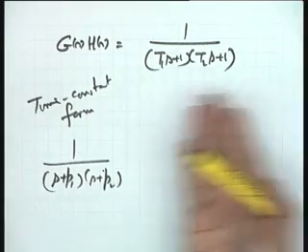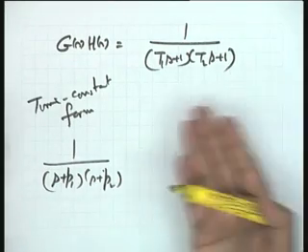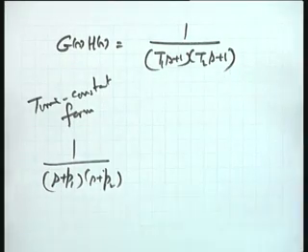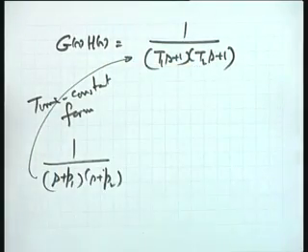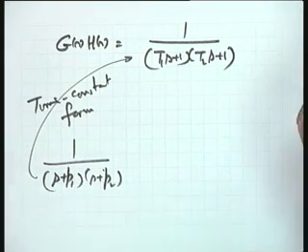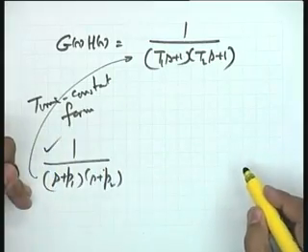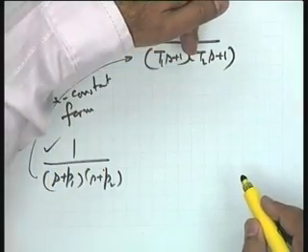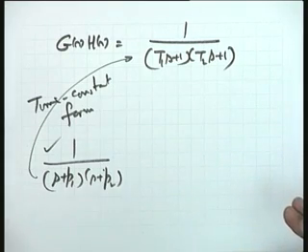It is quite obvious that the sinusoidal transfer function and the angle calculation become straightforward when the transfer function is written in the time constant form, and conversion of this form to this form is straightforward. So you take this as the first step of any frequency domain analysis or design method. If the transfer function is given to you in the pole-zero form, do convert it first of all into the time constant form, so that the analysis becomes convenient.